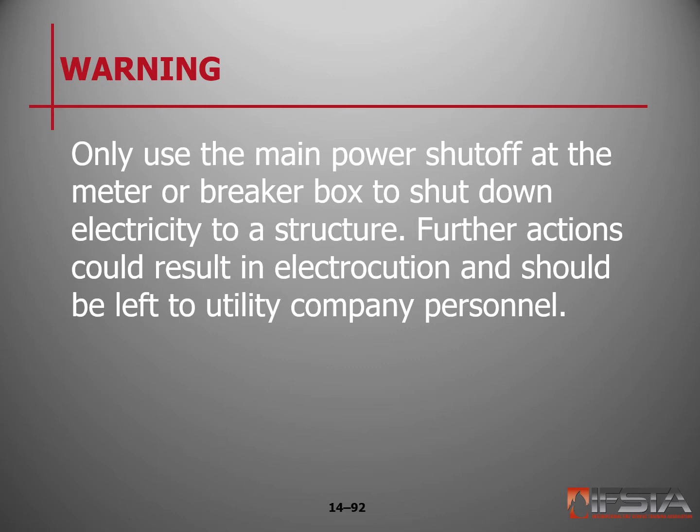Typically, the questions that we get here are about removing meters from meter bases. You have to be careful in removing meters, because if you don't get all the lugs taken out at the same time, you can cause an arc. You can cause a meter to explode, and they are like a grenade when that happens. And we've got to realize that the electricity can arc up to 3 feet. So if you're not trained to disconnect and remove a meter, then we shouldn't be doing so.